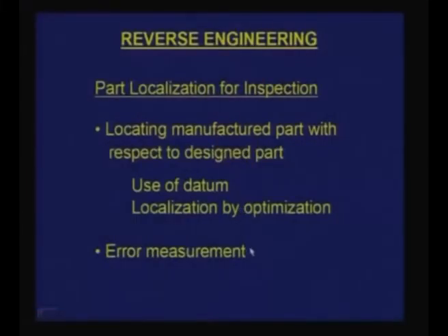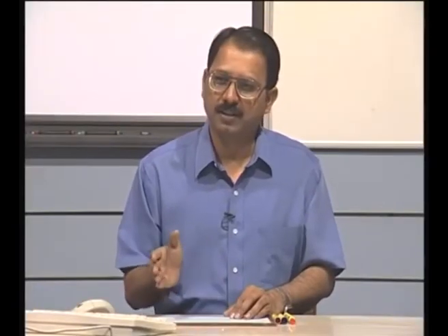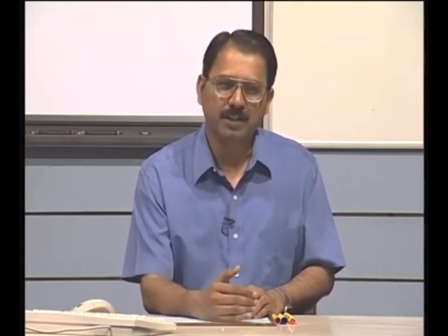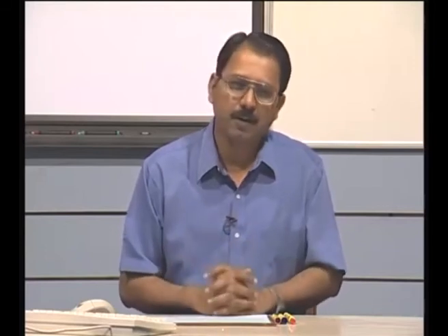So once I do a localization, then I can actually go and measure the errors and say, based on this particular localization process, whether the manufactured object really meets the design requirements. That means whether it matches with the design geometry within certain tolerances or not can be checked as a part of this particular aspect. Okay, so this is, you can say, a final application of this. So this is in brief about what I basically wanted to cover as a part of reverse engineering.